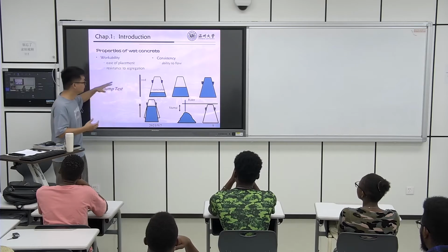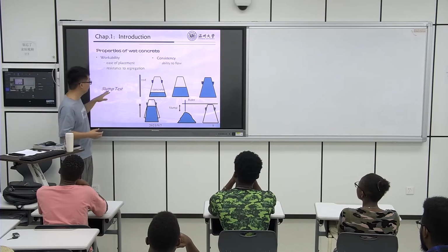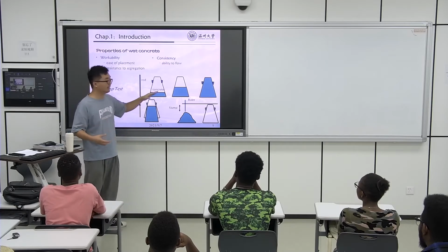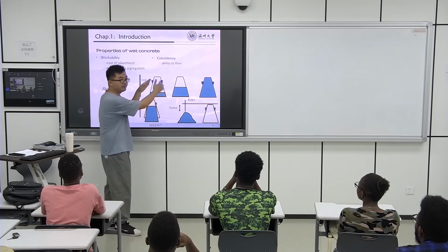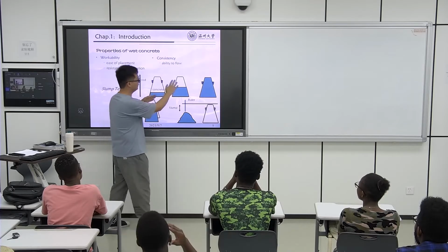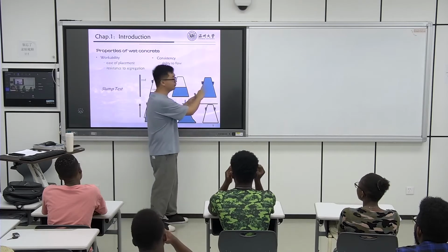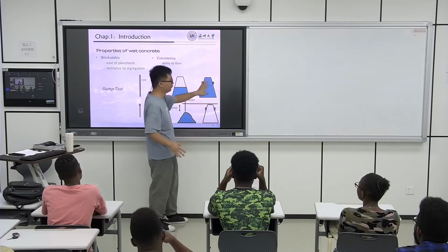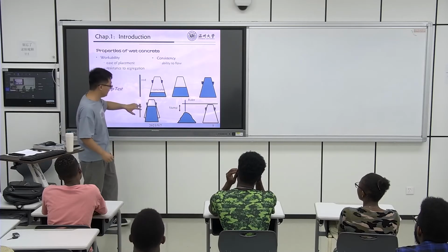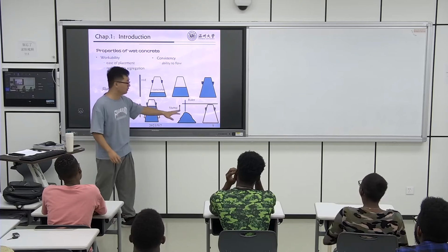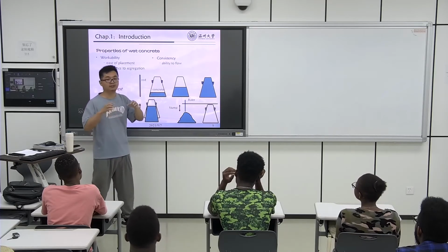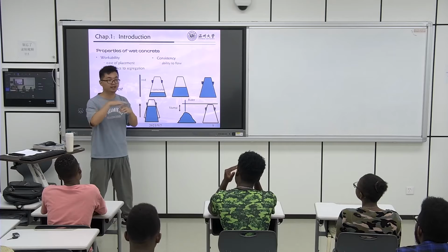Okay, so here I introduced this test. The process will be like this. This is the sheet we get here, and pour the concrete to here, and fill it. Then we remove this sheet, and of course it will slump, right? Because initially it is wet, it will flow.